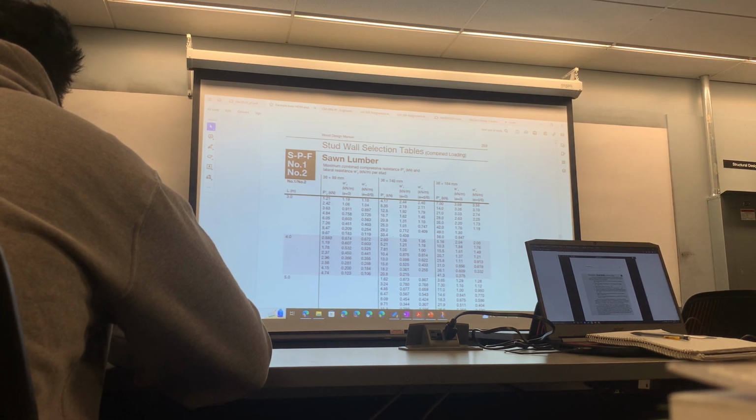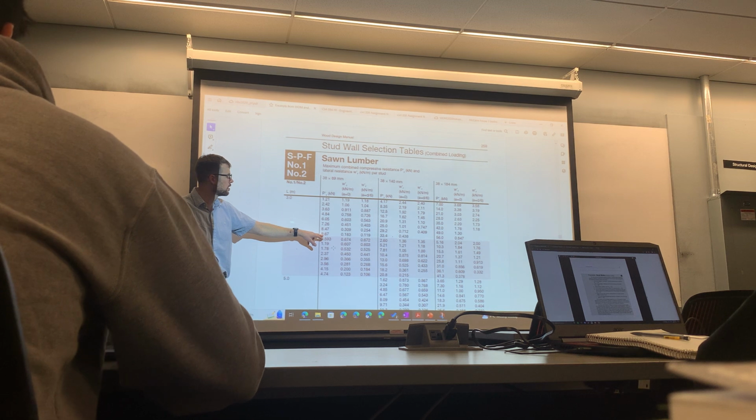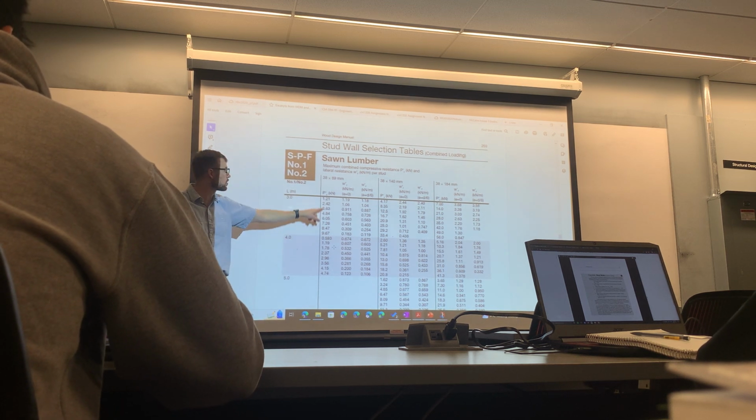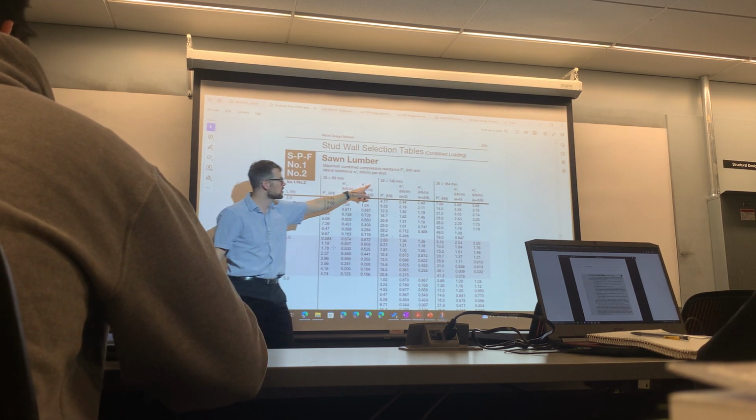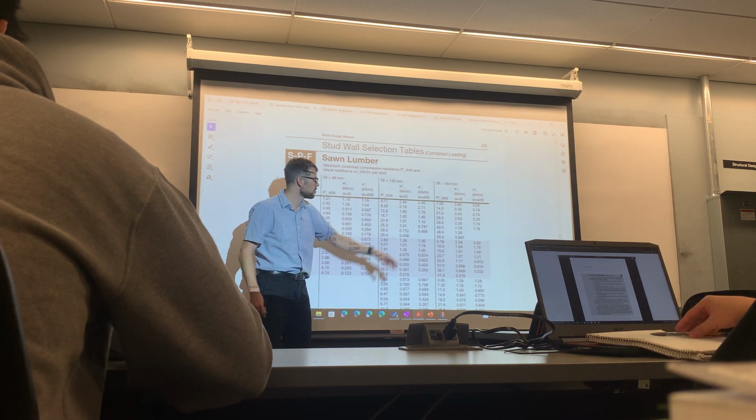But as the wind increases, your axial capacity decreases. You see that? So basically we're going to do this in 2 stages. We're going to say, what load can it support? This is up to 9.67 for a 2x4 wall. And then 2x6 walls, 33.4.